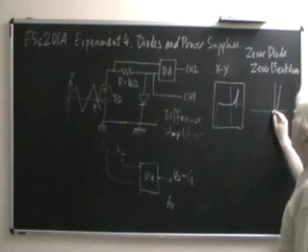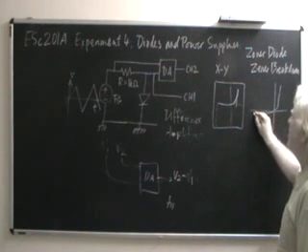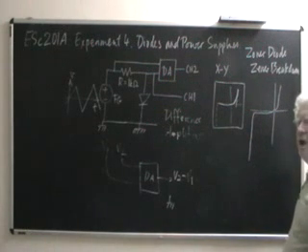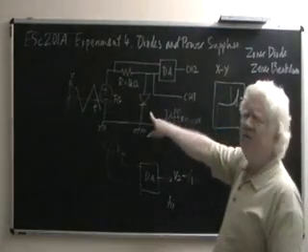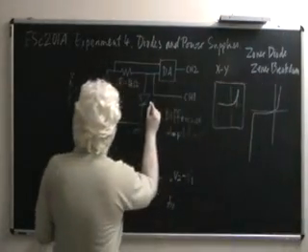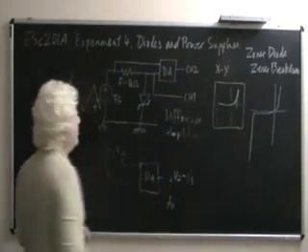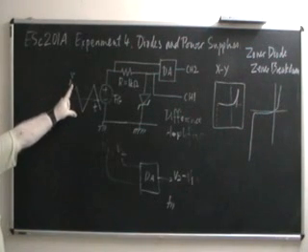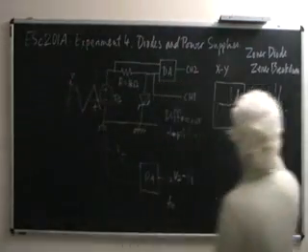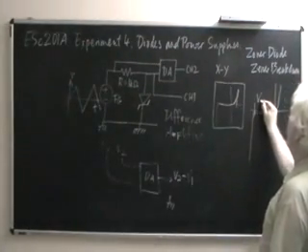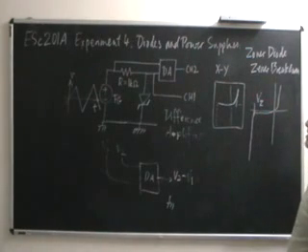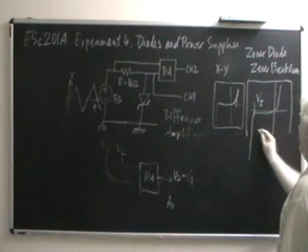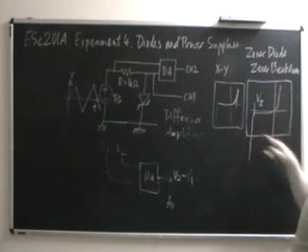This is the forward characteristic, a small reverse saturation current, and then a nearly vertical line. Now, if you replace this diode in the circuit by a Zener diode, whose symbol is this, and apply a signal here of sufficient amplitude to cross the Zener breakdown voltage Vz, then your screen would show you something like this.